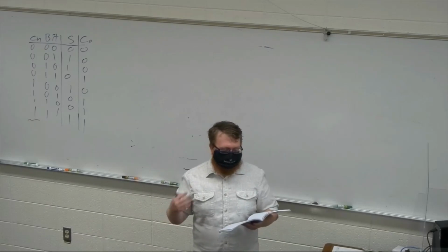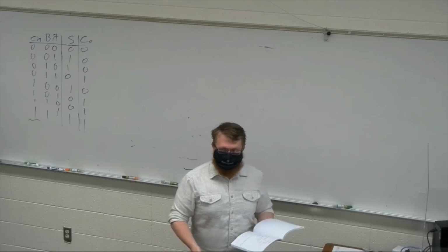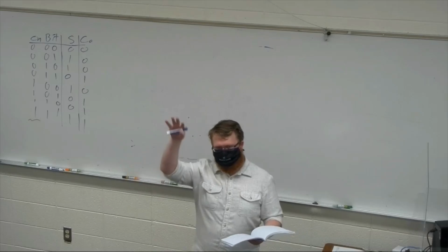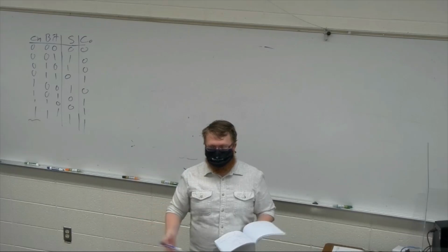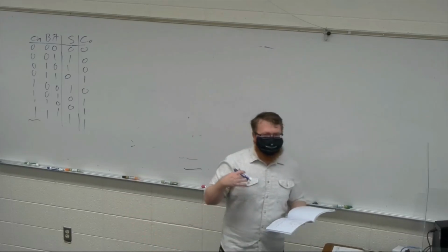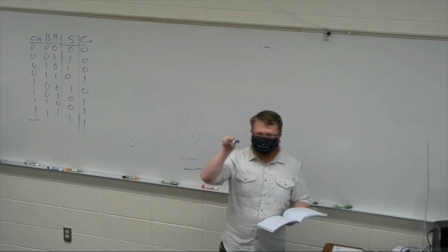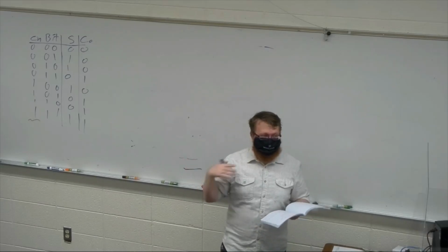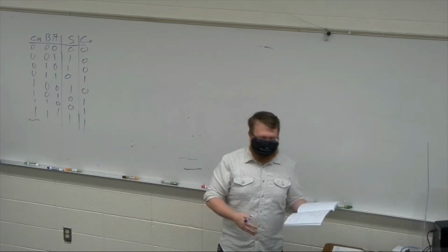So the general idea is that you can do multipliers a couple different ways. You could build a combinational multiplier, which is where we draw out the truth table, right, and we draw out some circuits, and it has inputs and outputs, and we're done. The problem with these is they're huge. They're very fast, they only need a couple of gates, but they're very big. You can do sequential circuits where you just step through each individual bit. These can be very small, right? It's basically just a state machine. These are slow, but they're very size efficient.